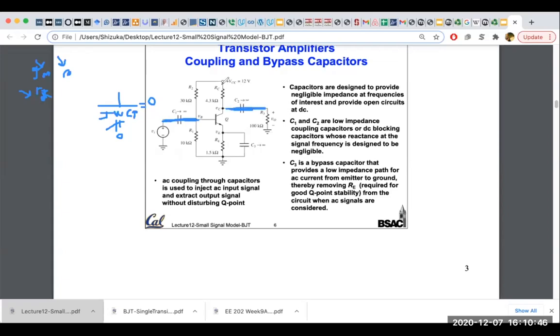And let's assume instead of this resistance, for simplification, it is an inductance. In AC, this is j omega L, and omega is not 0, but L is huge. So this is a big impedance. So that means this is open, for instance. Because you don't really need a DC voltage, you are just looking at the AC analysis.